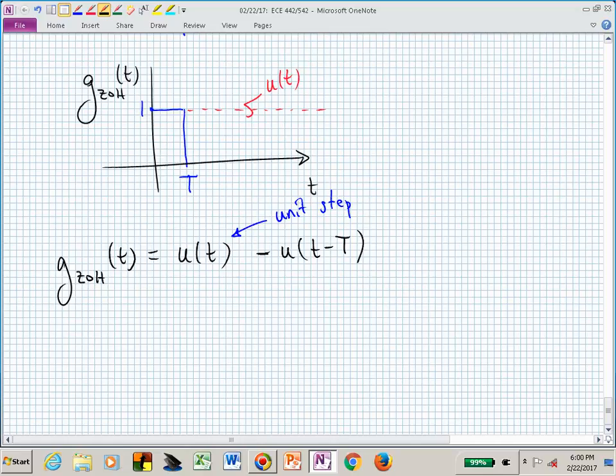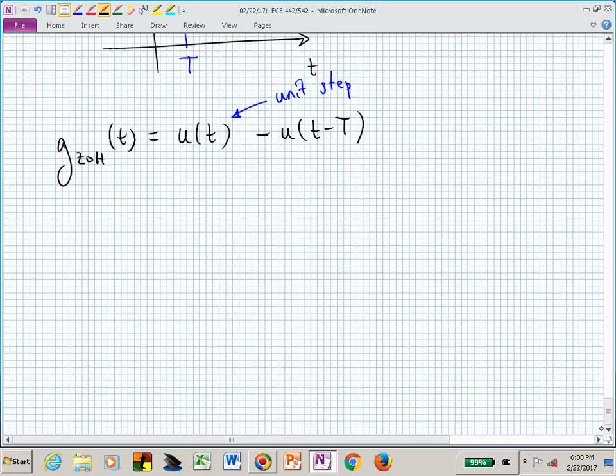So this makes it easier for the analysis or the description. Multiplication in the time domain would correspond to convolution in the frequency domain, and we get a little nervous when we start talking about convolution. That's the whole point of going into the frequency domain. We're trying to make it easier.